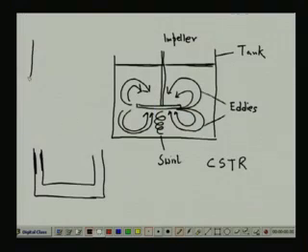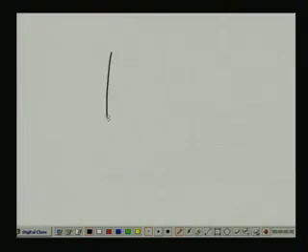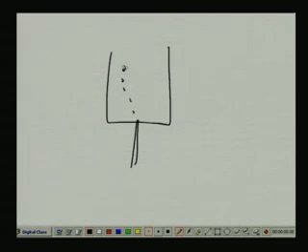There is also the bubble column reactor. In a bubble column reactor, if I take a new page, the oxygen is purged through a pipe and goes out through the liquid like this. Here again you will find that the oxygen is getting dissolved through this bubble column. There are various methods of getting oxygen dissolved, but you have to measure it continuously, either through a galvanic sensor or through a polarographic sensor.